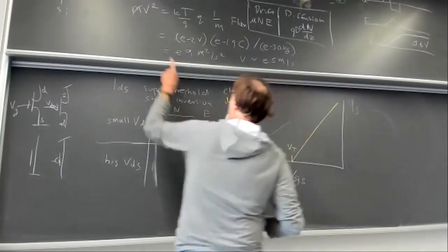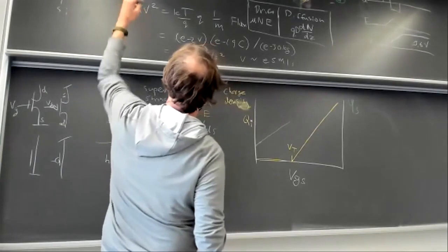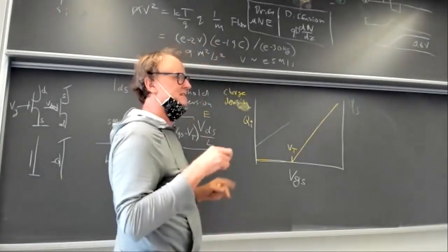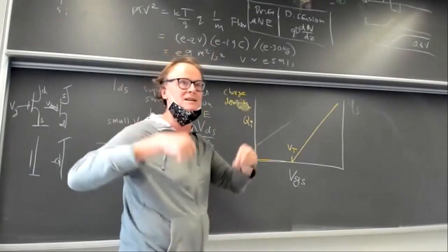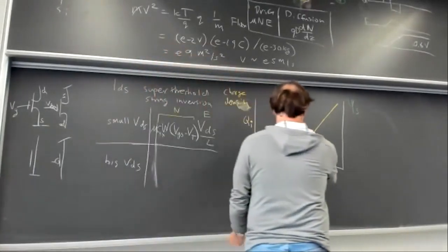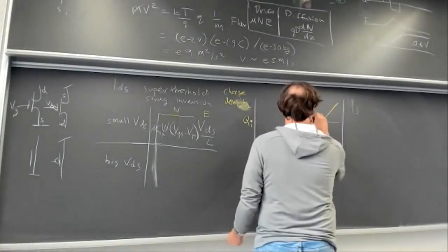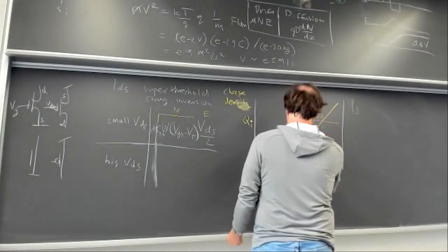And then as you go above threshold, charge is rushing in from the source. And so what happens is the surface potential gets so-called pinned, gets stuck down. And so then it only increases logarithmically, very slowly. It's pinned. And that's because charge is rushing in.